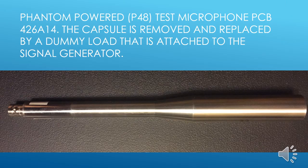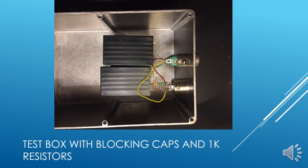So this is the microphone, quote-unquote microphone, because here's this dummy microphone capsule and then the 48-volt preamp in here. And then this is the box with the small 1K resistors and these blocking capacitors. So that was the physical test setup that was used.